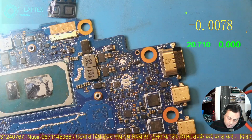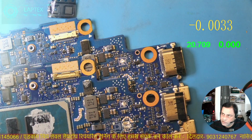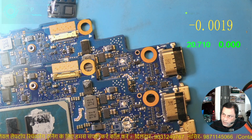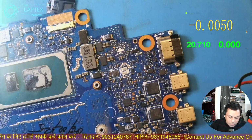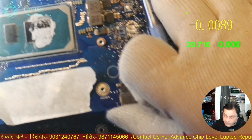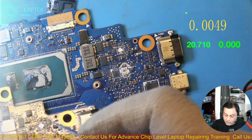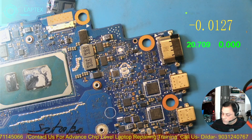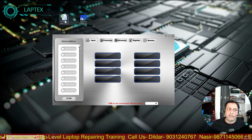So I have two motherboards where the MPS 2940A is used. As he said, I am going to do the practical on the boards. I have taken a backup of the particular model. This is the faulty motherboard I have taken for reference, and I have taken out the core IC and taken the backup. I'll show you what type of backup it gives. Here is the Excel file which is saved.